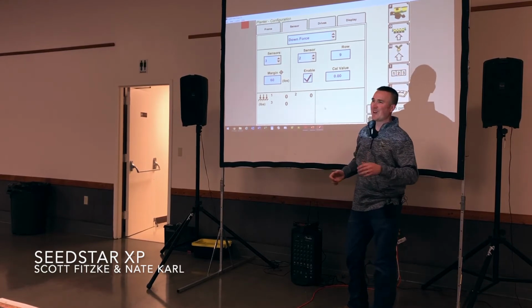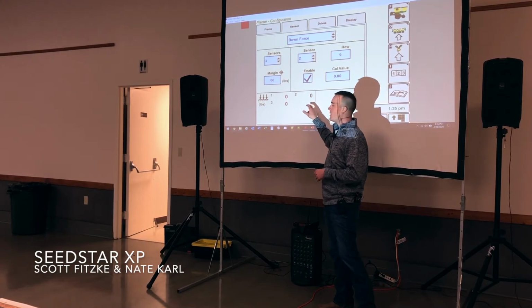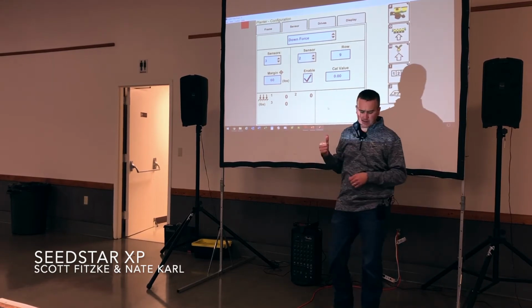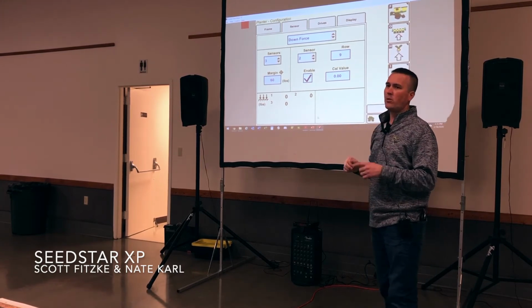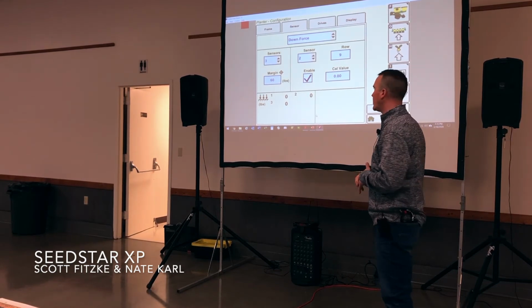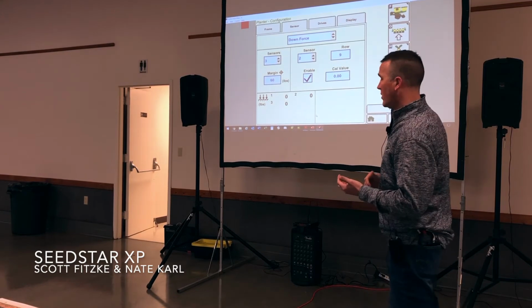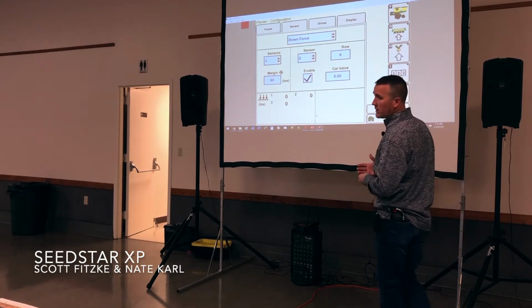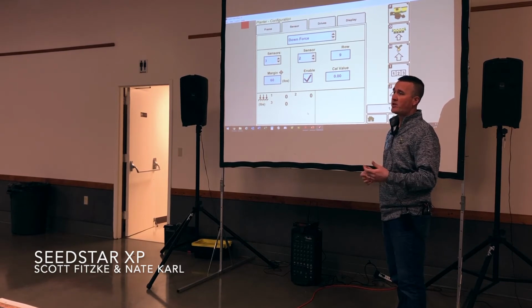It's a simulator, so you're going to have to take it with a grain of salt. But more importantly, if the planter was up in the air and I did not see those sensor readings at 0, we're going to want to reset or re-zero those sensors out so we don't have any bad information. I know some guys will reset this once a day. I would say at a minimum, once a week, or if you're doing any type of hybrid changeover, crop changeover,